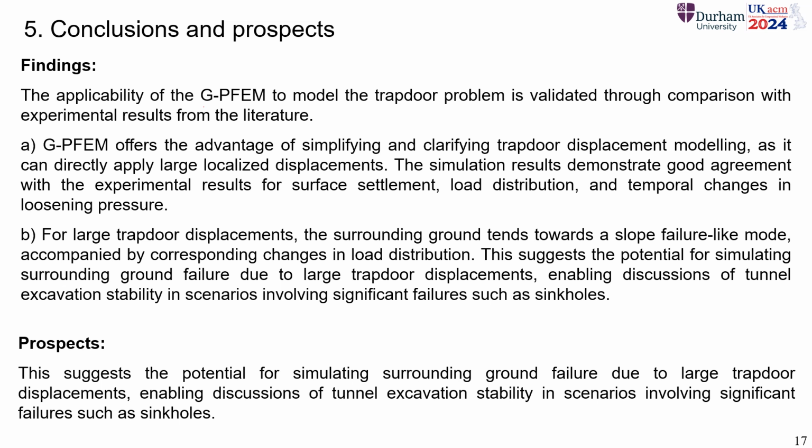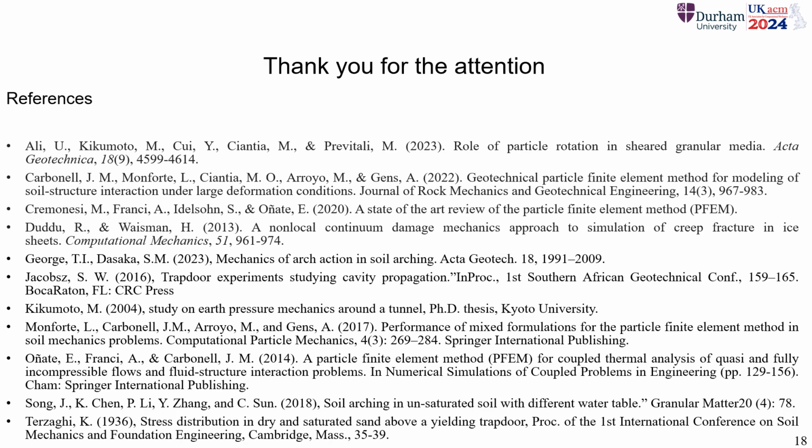The simulation results match the experimental results surprisingly well for surface settlement, load distribution, and temporal changes, while for large displacement the overall mechanism changes significantly, which means that using this large deformation numerical modeling becomes much more important than for small deformations. And so this method should be used in the future to investigate tunnel excavation. Well, thank you for your attention.